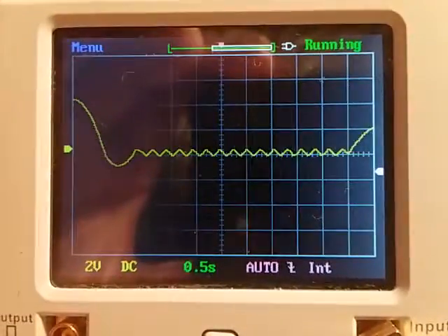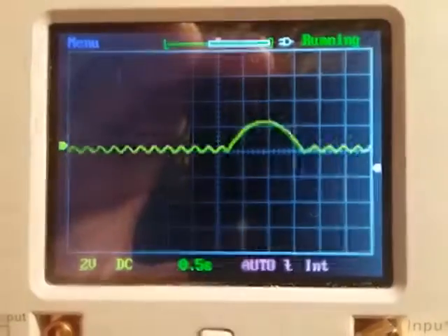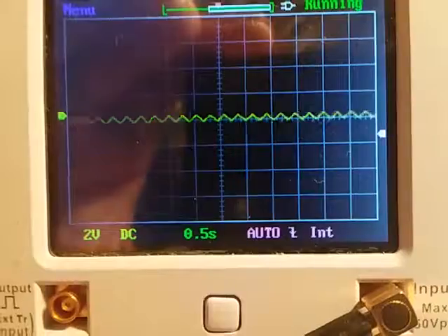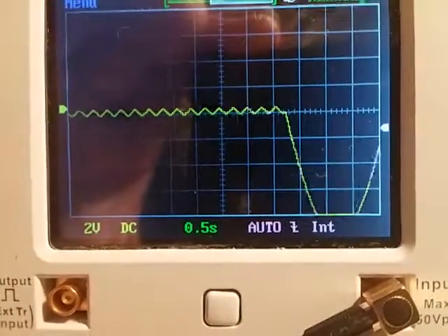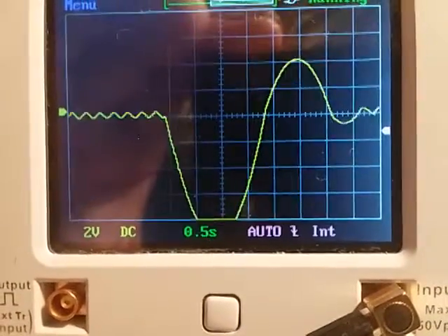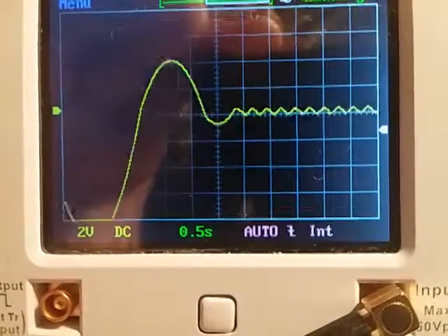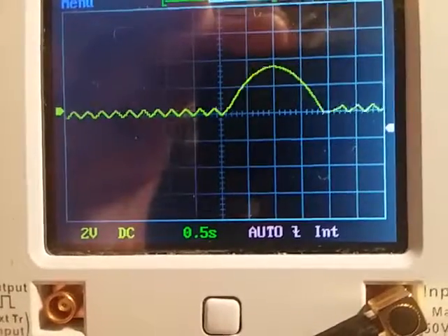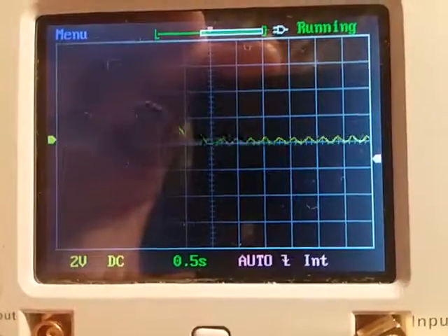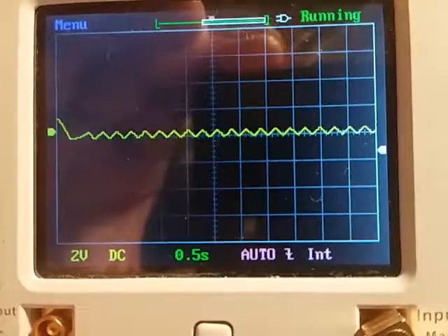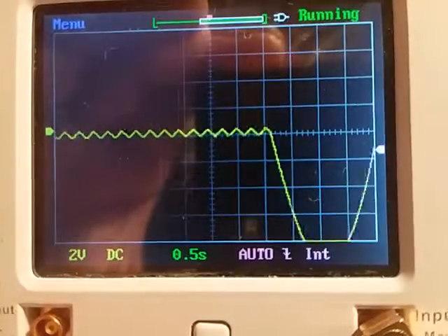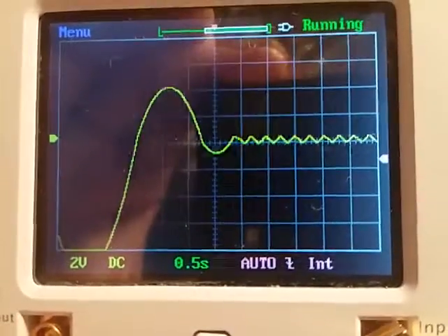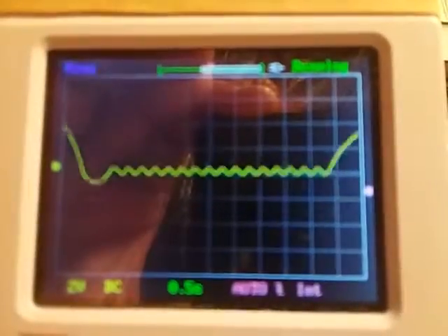Here's the error signal. The error signal controls the motor, but it goes through hysteresis, and so you see this oscillation of about 3.5 hertz. During the servo step input, you will see an analog response as shown on this meter, and a continuous oscillation due to the searching action across deadband, or the hysteresis circuit.